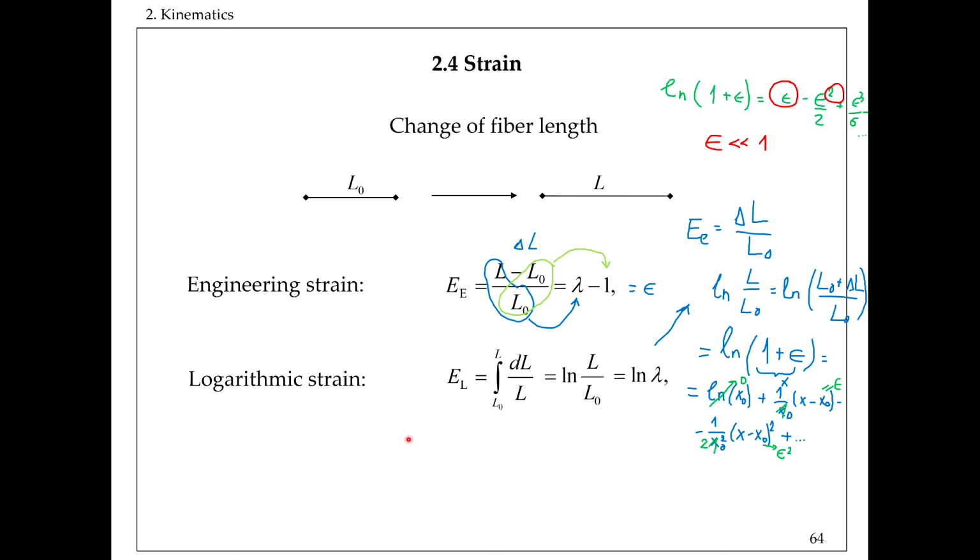And hence another measure that I can introduce here is called the Green strain, and it basically takes exactly this higher order change in the strain into account. So you see that suddenly we decided not to calculate the linear change in the length, but rather to calculate the quadratic measure of those.